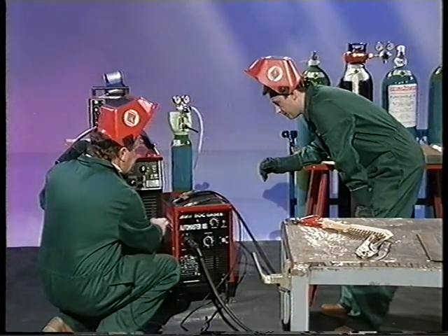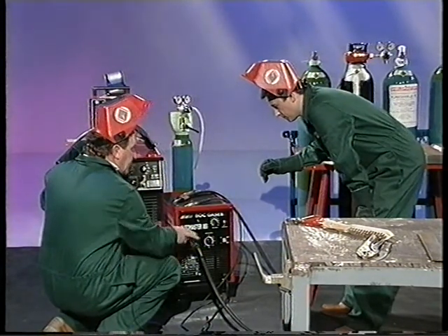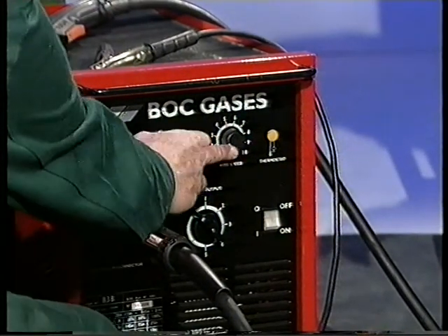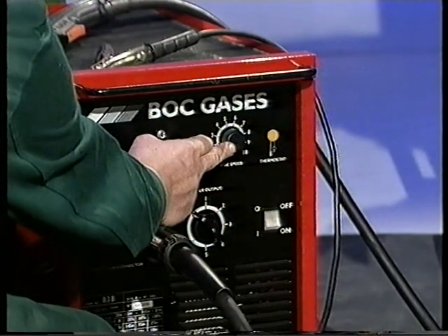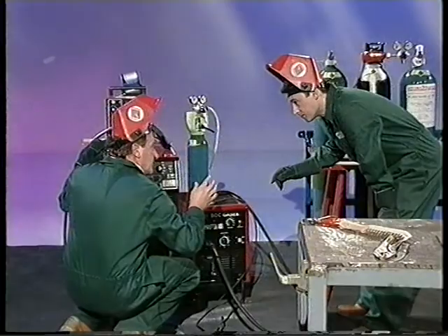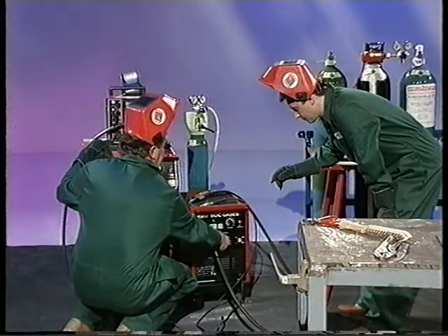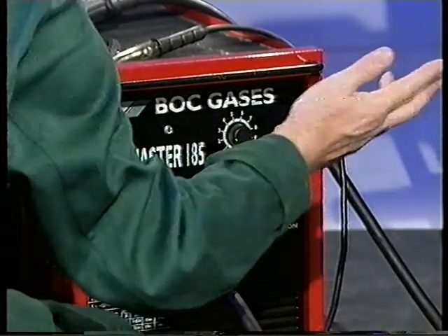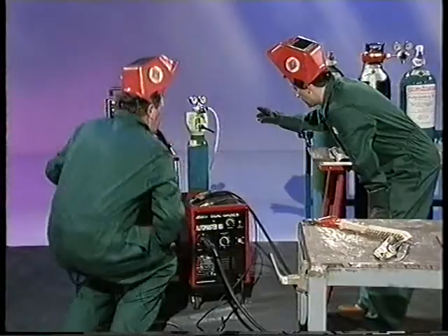This is also single-phase supply compared to three-phase supply over there. The wire inside the machine, it's the same principle, comes into the line and the torch and is fed through. The controls on the front: there is the wire feed speed, or amperage in this case, and here's the voltage control. Instead of having the sliding voltage control that we had on the previous machine, this is stepped voltage control. And you'll probably find that each one of those steps is 1.5 to 2 arc volts. Right, and the gas is set ready.